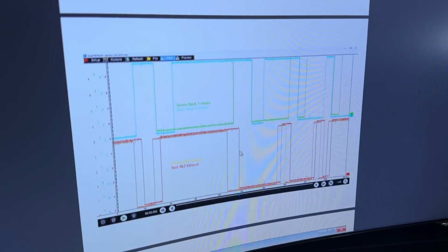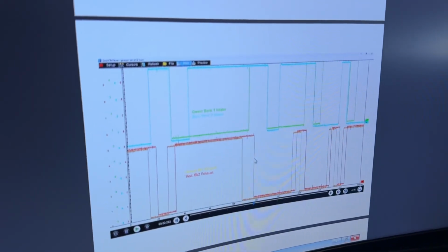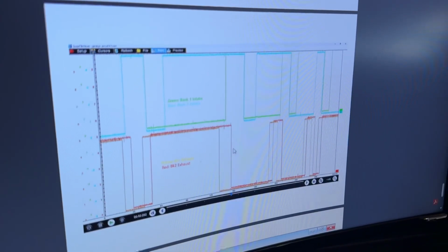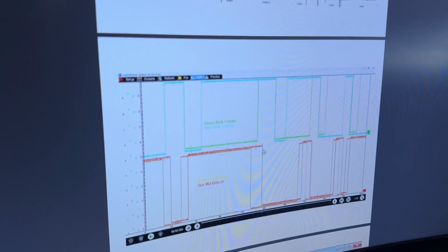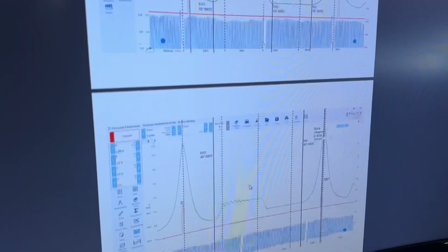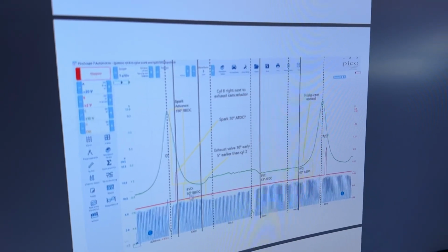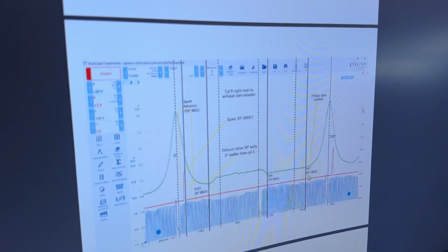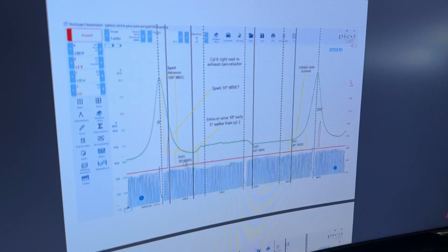The other thing is, this particular car starts when you unplug bank 2's exhaust camshaft sensor. It fires right up perfectly. Otherwise, it'll sit there and crank forever and try to start, but won't start. So at any rate, our bank 2, or our left exhaust camshaft sensor is falling at the wrong time. What's really interesting is if you look at the captures, notice here's bank 1, 40, 60. It's the one we just did. Okay, look at bank 2, 50. Exhaust valve opens at 50, but notice the intake is still right, 60. So there is variation in the camshaft on bank 2 exhaust.